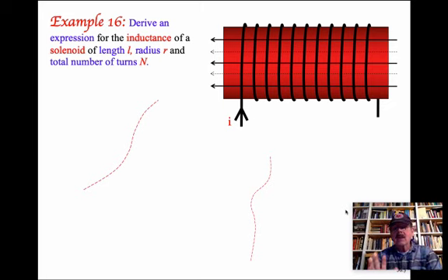There is a similar problem for inductors. You have some geometry, and you want to know the inductance of the geometry. The technique basically is that you use minus N dΦ/dt, Faraday's law, equaling minus L di/dt. You'll notice there's an L in there, an inductance value. So you have to figure out what the flux is, and you take the derivative of the flux. That's the dΦ/dt part. And you just fuss with the relationship, and by the time you get done, you have an expression for L. And so this is an example.